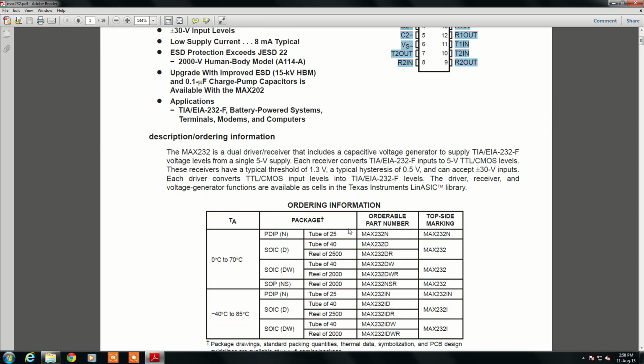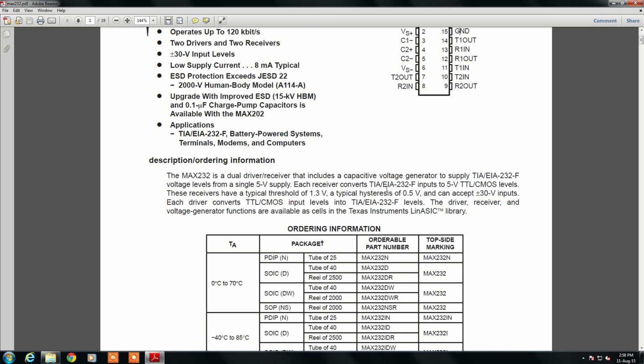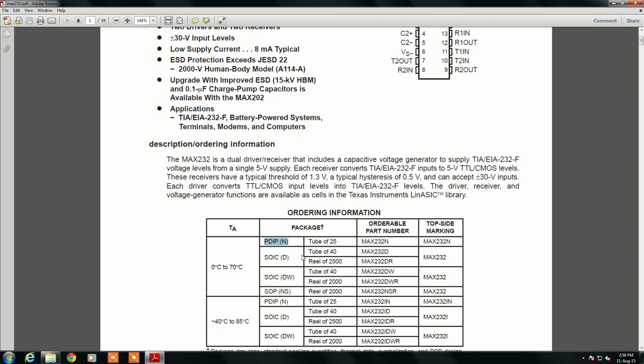So whenever we design the circuit diagram by using some software, one has to remember the component and one should remember the package. If the package is not available, then you need to create the package on your own. This will happen because time to time new packages will be coming in the market and that package or the component might not be there in the software.